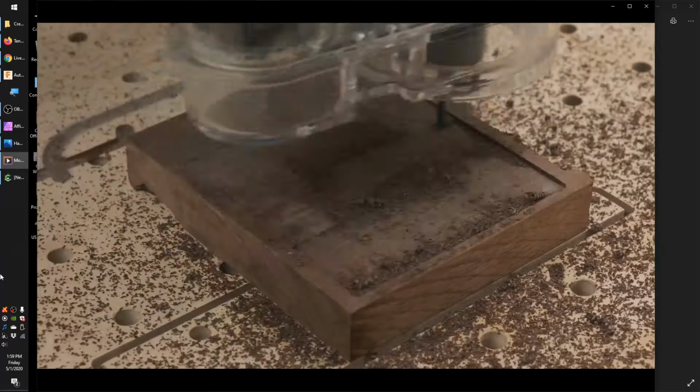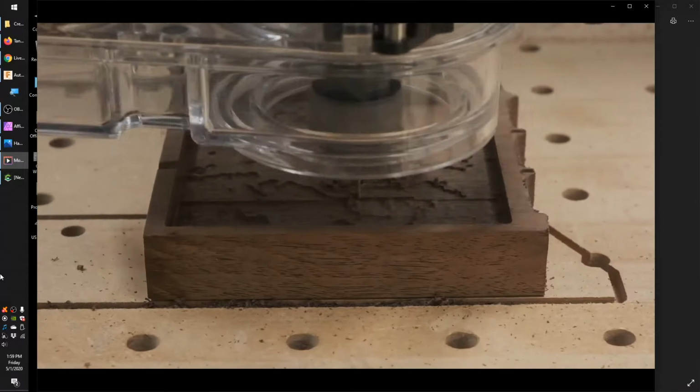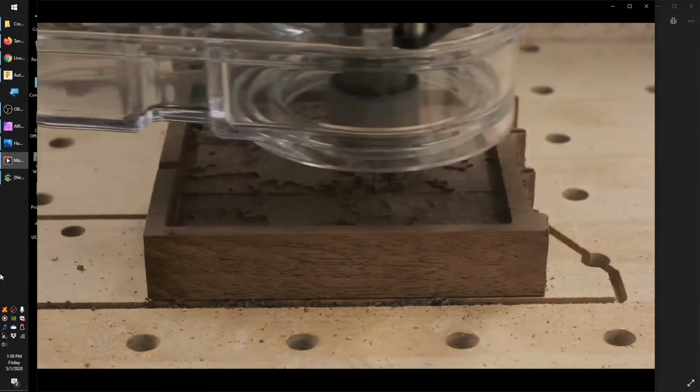All right, I clearly made this montage far too long, but this just illustrates the point that those last couple step downs are going to take a little longer. This is sped up, I want to say 300 times. My step down's about 7/1000 of an inch.